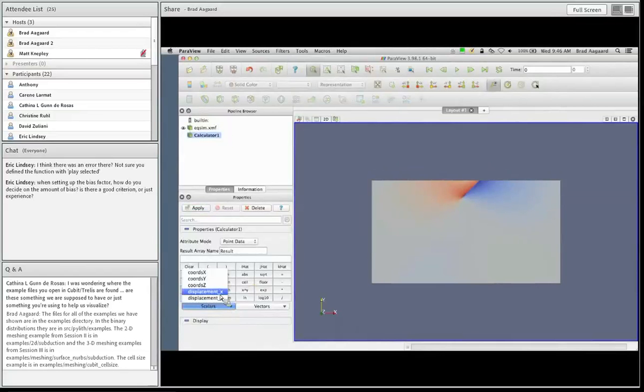And so now up here, I can select my displacement vec. So here's the magnitude of that vector. And you can see now I can warp things. So let's warp by a factor of, I think, 1,000. And so there's our reverse fault. Notice our slip. So we've created a reverse fault earthquake. We have observations along the ground surface.